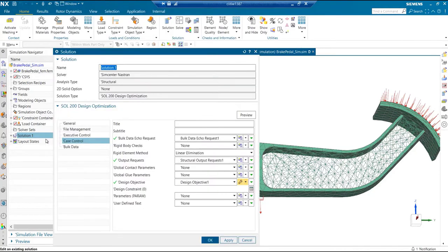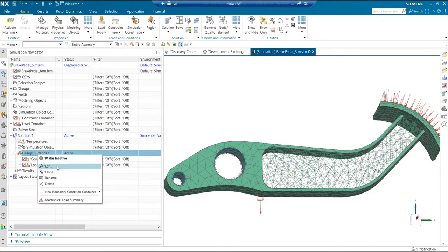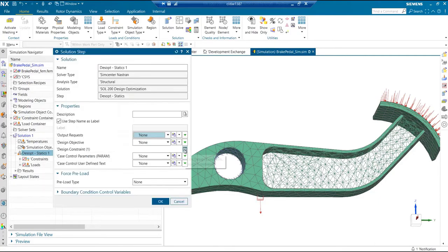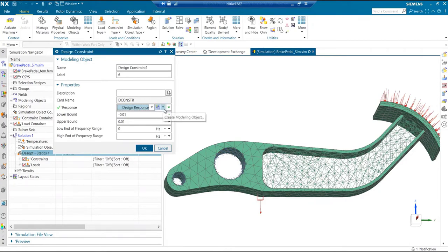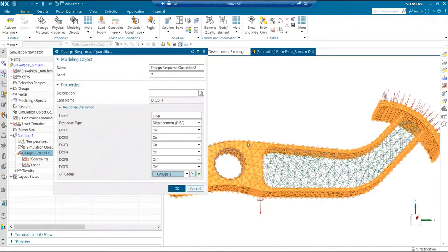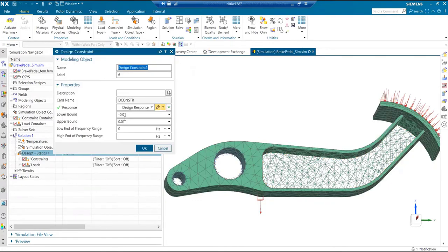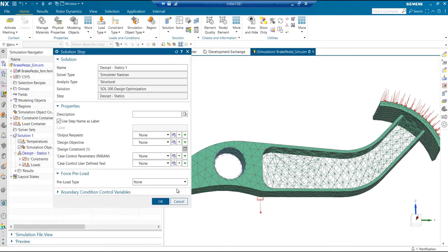And we also have another constraint. In this particular scenario, we are just trying to limit the displacement of all the surrounding body nodes along X, Y, and Z to between minus 0.01 and 0.01. So I don't want any of these to move beyond this value.